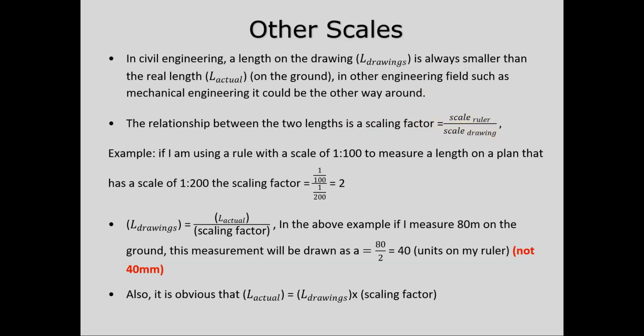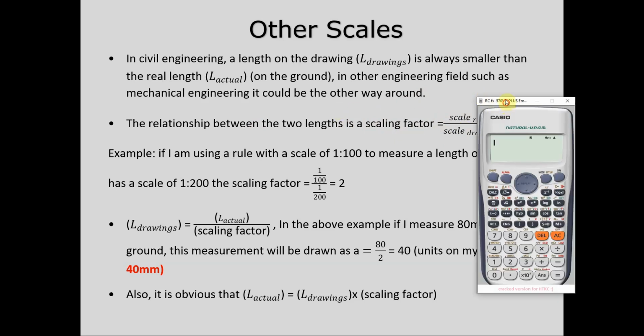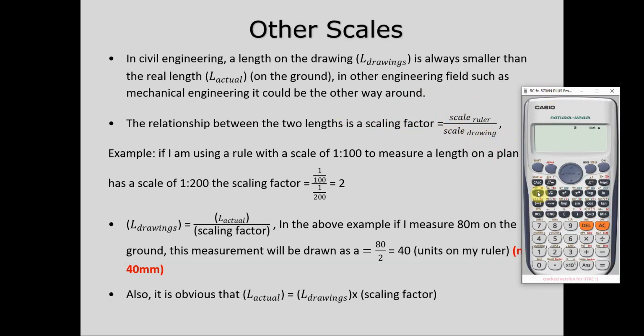So let me get my calculator. The scale of the ruler at the top, which is 1 to 100, as we agreed, and the scale of the drawing is 1 to 200. Divided, that will give me my scaling factor, equals 2. I've got another example here. I'll talk about this example in a minute, but regardless, let's carry on with this example that I'm doing. By coincidence, it came with the same scaling factor. This is my scaling factor.